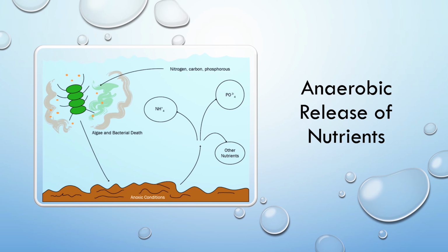Normally, the free nitrogen and phosphorus from the anaerobic layers will bind to sites on particles in the aerobic zone. However, if there are high levels of nitrogen and phosphorus being released, all the sites in the aerobic zone will become filled, and that free nitrogen and phosphorus will be released into the water column. Some metals can also be released in this manner as well.